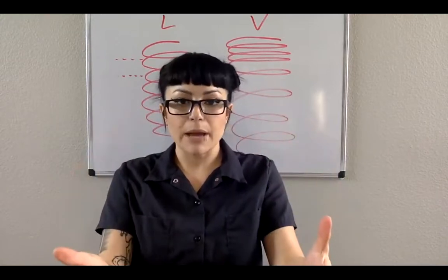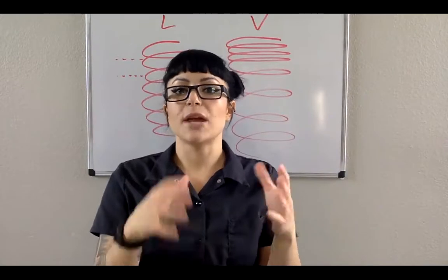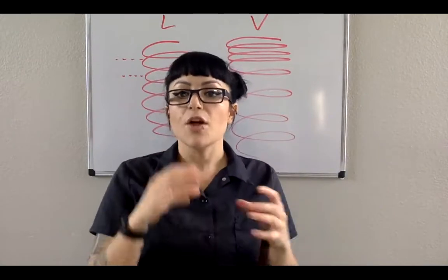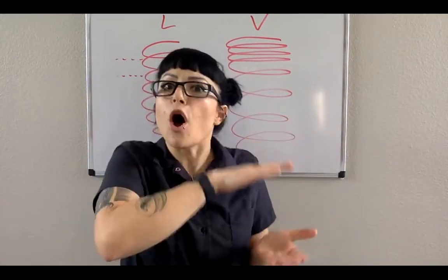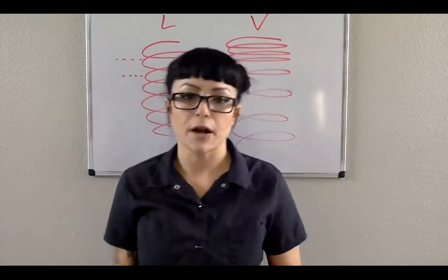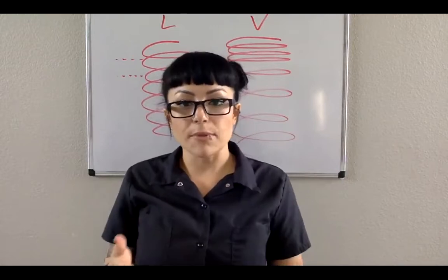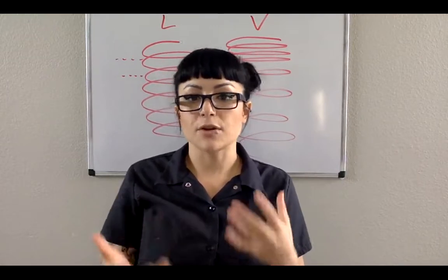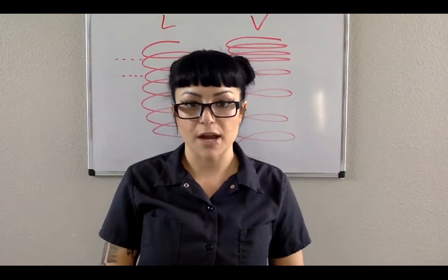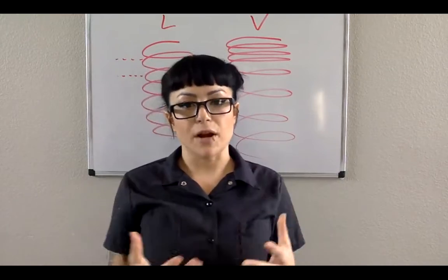That's what we're talking about when we get into a stiffer spring rate, variable rate. The more I compress the spring, the harder it gets to compress on a variable rate. So if I'm leaning into a corner, that's going to help me with my weight transfer and control and traction and all that fun stuff, right? So that is going to be your variable rate spring.